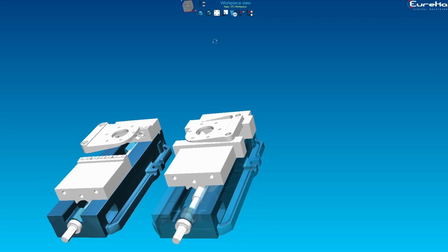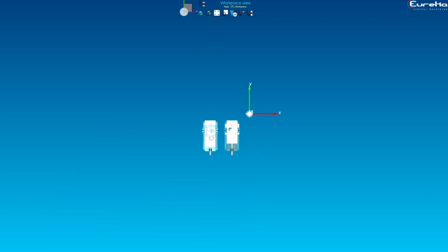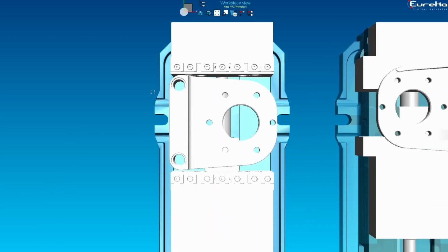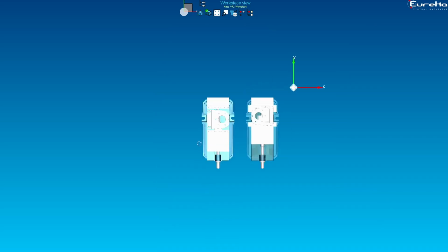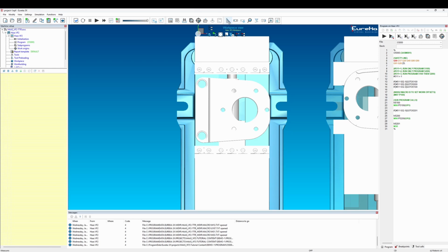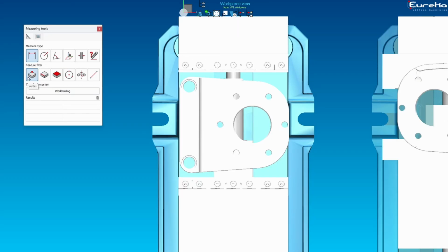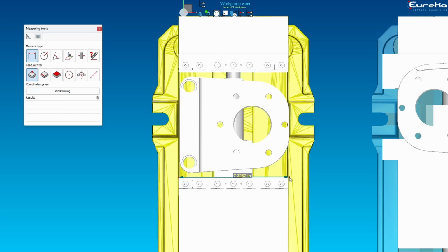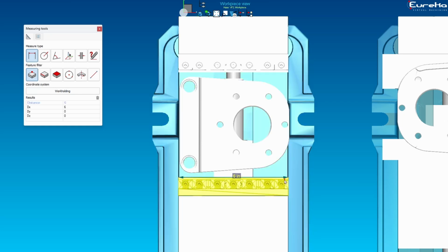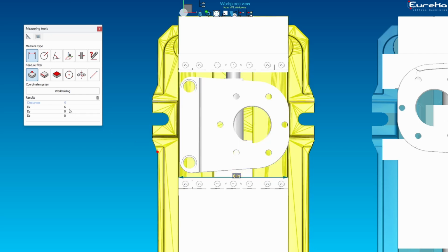Let's go to a top view in our workspace. To do that, click this top face on the view cube. And then let's zoom in on the part. I want to switch over to an orthographic view. So I'll click this button here and I'll zoom back in. Let's open the Measure tool. You can measure distance between vertices. Let's go to our selection mode and click two vertices. And we'll see the measurement is here in the workspace, as well as here in the measure window.